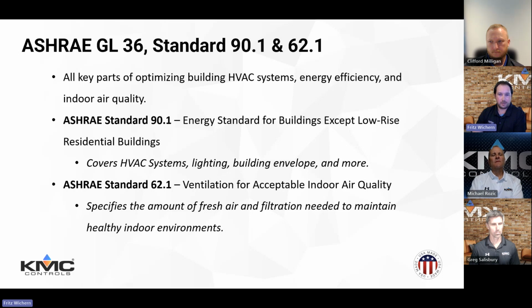Then the ASHRAE Standard 62.1 just covers the amount of fresh air and filtration needed to maintain healthy indoor environments, which is obviously key with COVID-19 and a lot of new standards coming into our systems across the U.S. So it's just critical to maintain balancing ventilation efficiency and indoor air quality, so you're not overtaxing your system, but you're getting enough fresh air in the buildings.